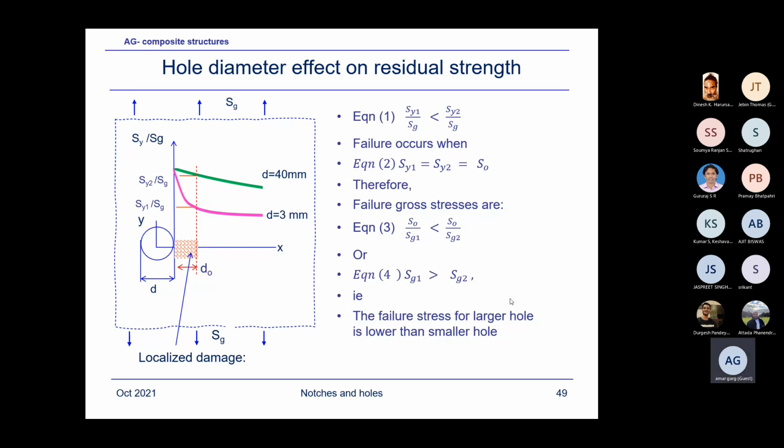Because if you use only one characteristic dimension based on, say, a quarter-inch hole, for larger holes it might be conservative sometimes. So normal practice is to calibrate the characteristic dimension for various laminates, layups, and diameters, and plot the chart in order to cover your design space.